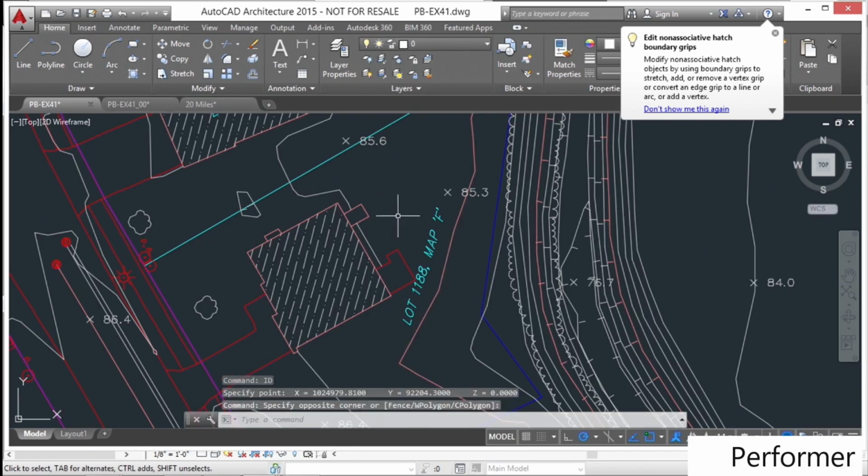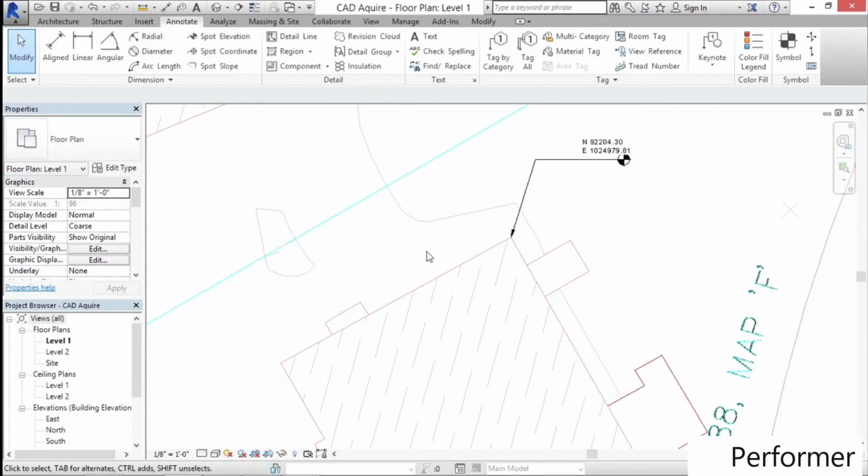So the only real advantage that we get from using the larger file that has the dummy object at the origin is that the coordinates that you query in both files are identical. So you're working with the same coordinate system sort of by default there. But that's a lot of trouble to go through to make that happen. And we have other alternatives available to us in Revit.